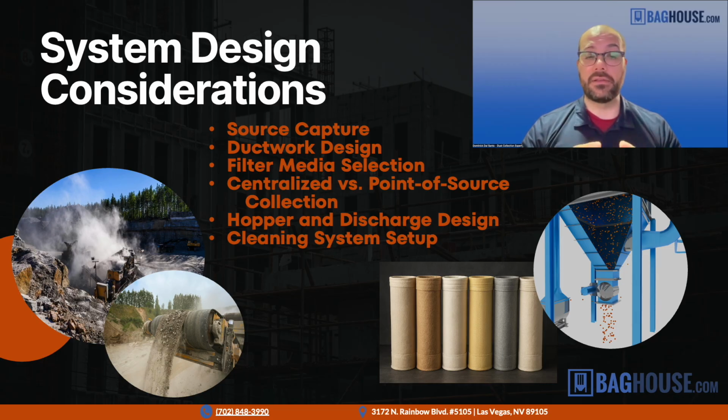And then another common thing that needs to be looked at is hopper design. Make sure that we have a sufficient design that allows the dust to be removed and not get stuck in there. So that may involve using things like vibrators or aeration devices to keep the material flowing and emptying out of the baghouse. But also, whatever comes under the dust collector, so the rotary airlock, and then whatever's underneath after the discharge, we need to consider that as part of the entire system.